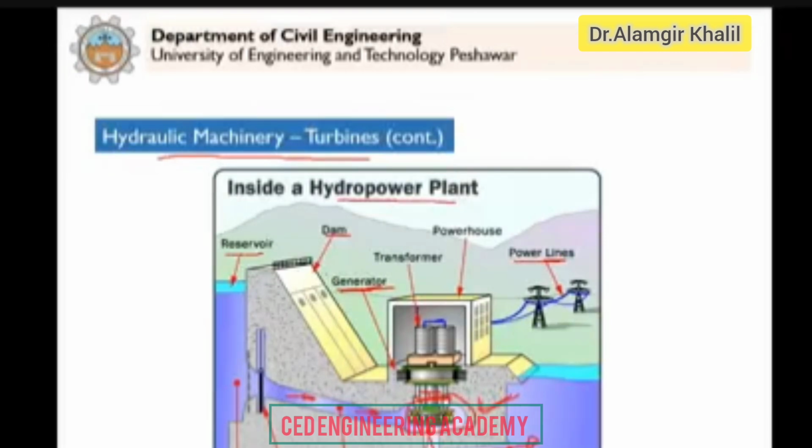In order to reduce the speed, you need to reduce the quantity of water supplied. How can you reduce the speed of rotation of this turbine? These are huge turbines. We do not have a button to stop and start it like this. So you have to reduce the quantity of water supplied. That will reduce or control the speed of this turbine. For this purpose, these control gates are provided in the case of a reaction turbine, because the wheel runs full. These gates are provided to control the supply of water to the turbine, so that we can control the speed of the turbine.